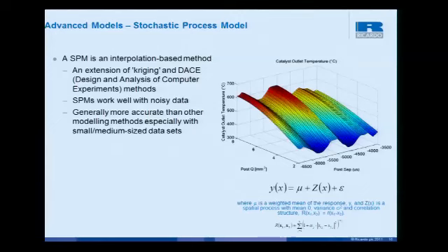This characteristic here, I'll just mention because this is a real engine characteristic, for anyone who wants to argue about whether polynomial models are suitable for modelling all engine data. This sinusoidal characteristic is caused by pressure fluctuations in the fuel injection system. So it's a real repeatable physical phenomenon. This was on an early multiple injection system, and it's not such a big problem these days. But you want a modelling system where, if that nonlinearity is there, you're able to model it.